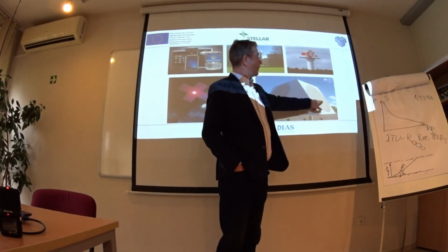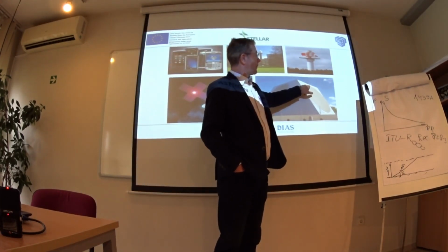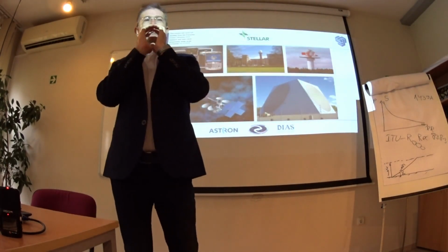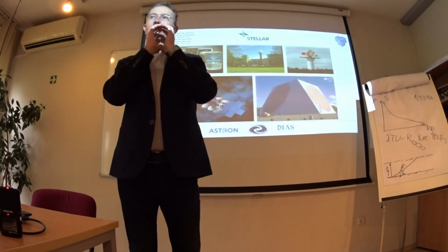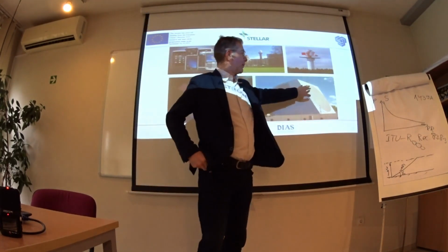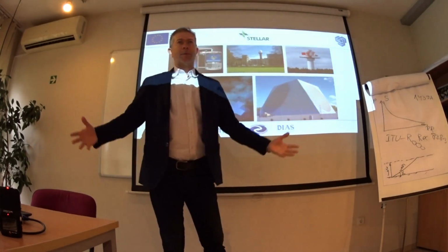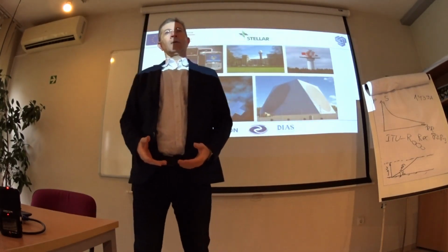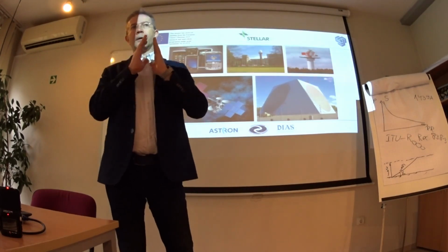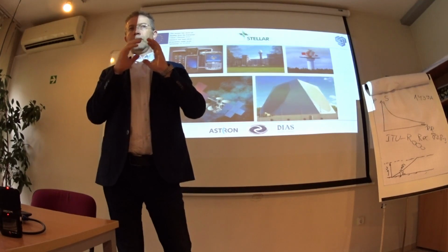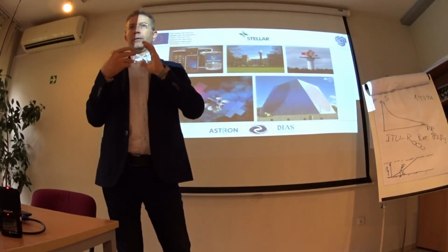This aperture here, every dot is a small feed horn. And then if we combine thousands and thousands of them, they form one aperture. And on this aperture we can very well control the phase and amplitude of the transmission and reception.